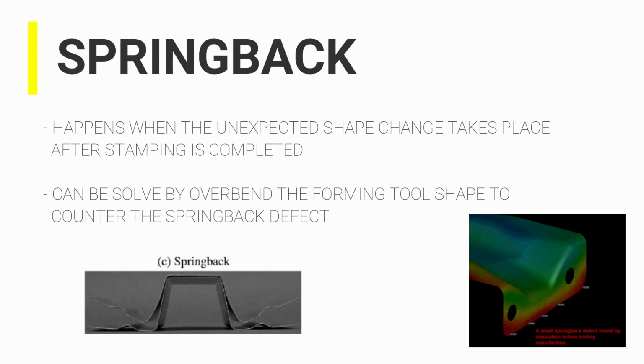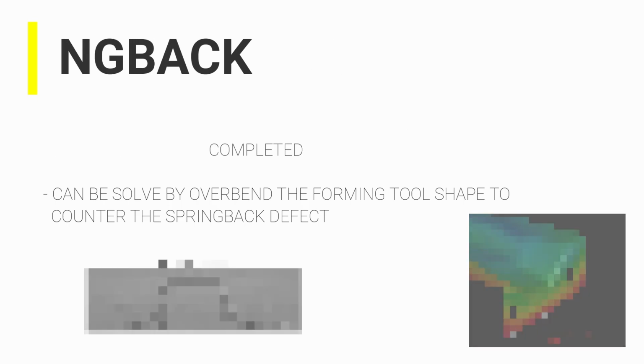However, this method alone may not be successful and sometimes more effective methods are required, such as inducing positive stretching to increase part strength, such that the product becomes stiffer and stronger than the original material, which leads to a reduction in springback.